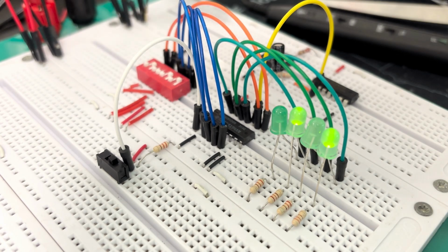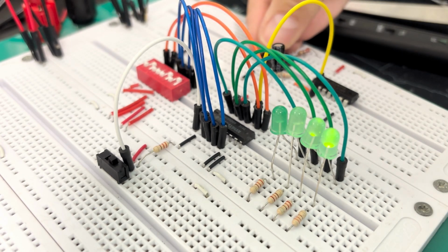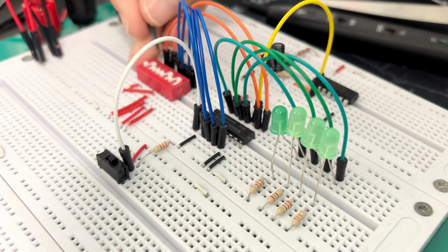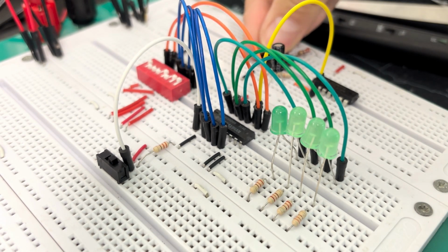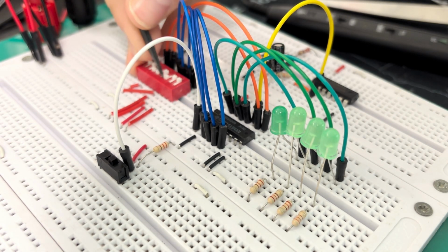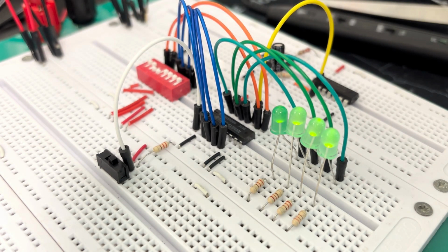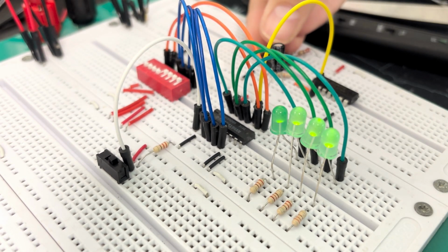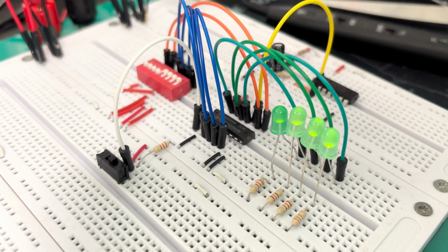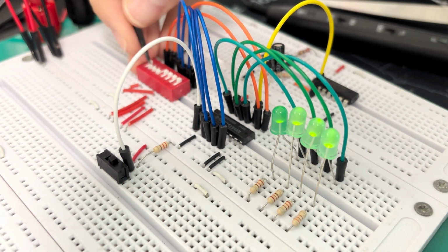In this demonstration, I start by loading the value 5 and then shifting it right. Then I load the value 11 and shift it left. I load the value 15 and then put the register into hold mode as I continue clocking the flip-flop. The register outputs do not change in hold mode. Finally, I load the value 10.